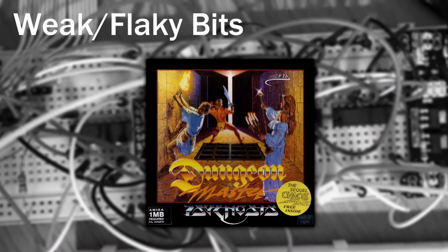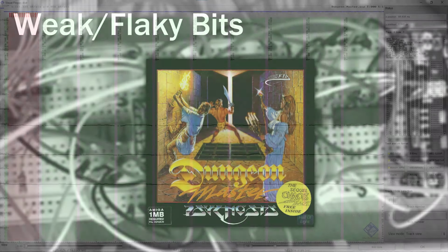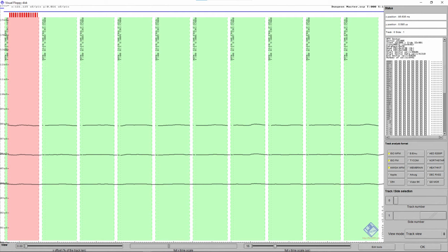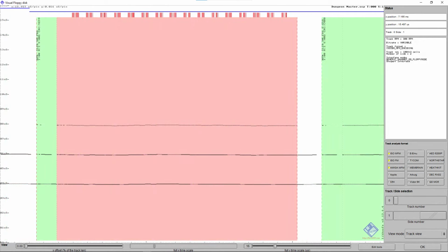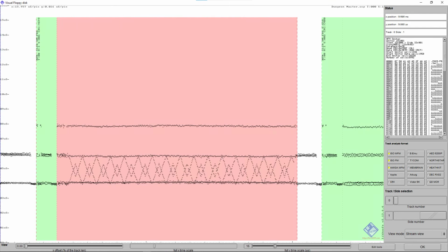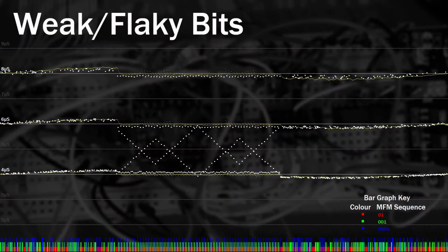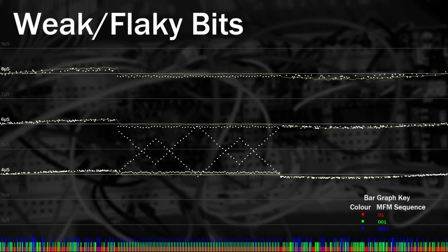This copy protection method worked by encoding some special data into one of the sectors. On track 0, upper side, see the strange sector to the left. Zooming in doesn't reveal much, but HXC doesn't like it. That is until we switch to stream mode. There's an interesting pattern going on here. This pattern is deliberately designed to confuse the PLL and produce edge cases where flux transitions can occur on a clock boundary. What really surprised me is, it actually worked on my simulator.